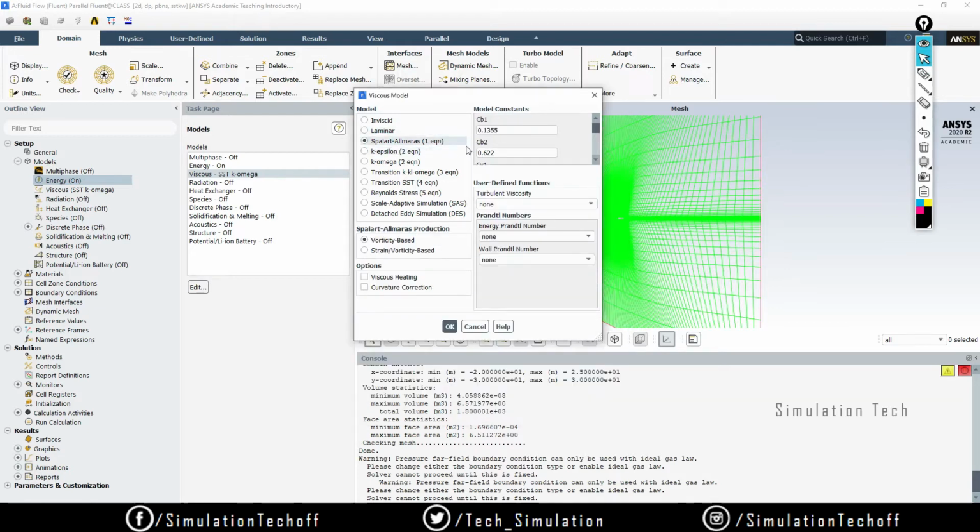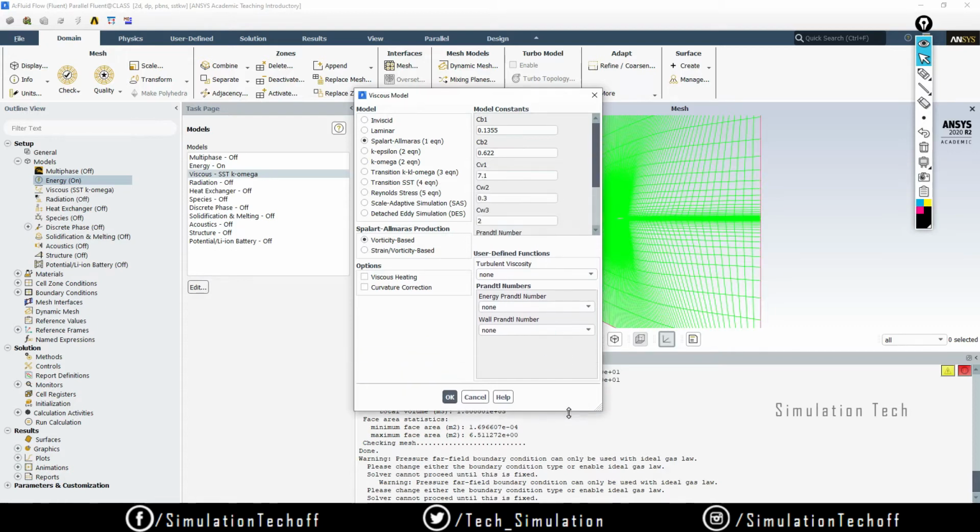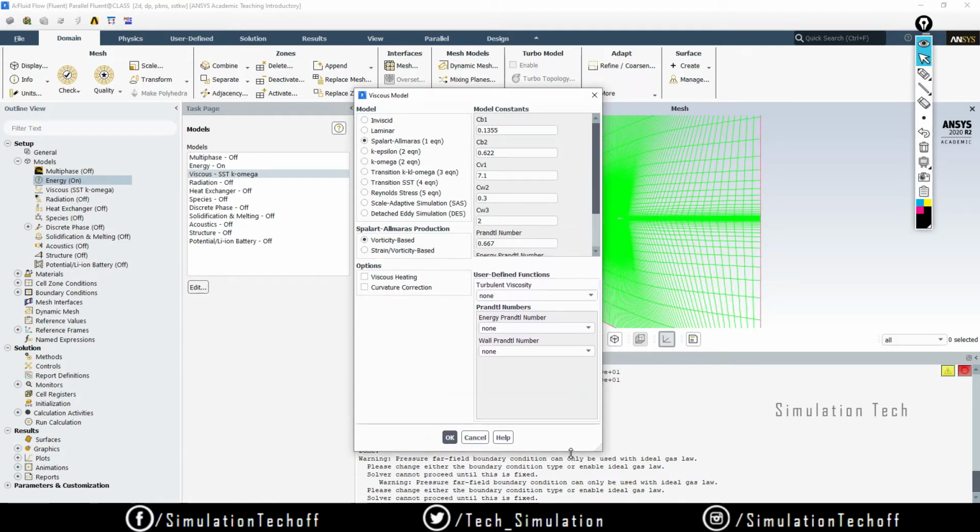It's a single equation model, more suitable for aerospace applications, where there is no wall bounded flow, and it's very good for convergence also. So we'll get convergence as soon as possible. With 1000 or 1500 iterations, it depends upon the mesh condition. If we don't get a converged result, we'll try to change to k epsilon or k omega itself.